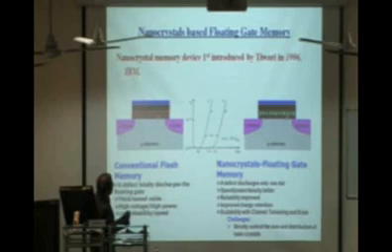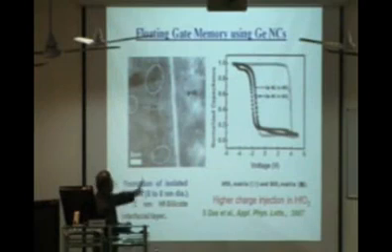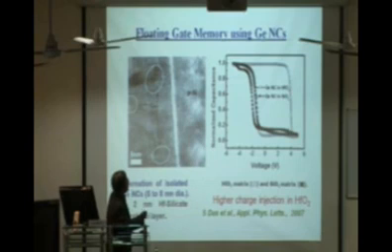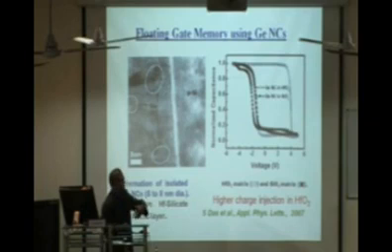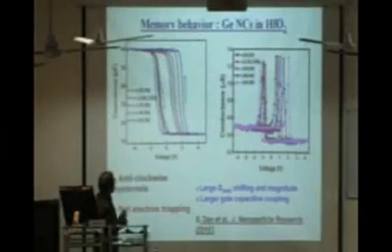So this can be used so that either state can be 0 or 1. That means you want a high threshold voltage and a low threshold voltage. And in fact, this can easily be seen by taking either the current voltage characteristics or the hysteresis in the capacitance voltage characteristics. We have seen that the hysteresis varies as a function of the size; if the density is more, the hysteresis is more. So ideally, this can work, and we have seen the hysteresis not only in the capacitance voltage, but also in the conduction voltage.